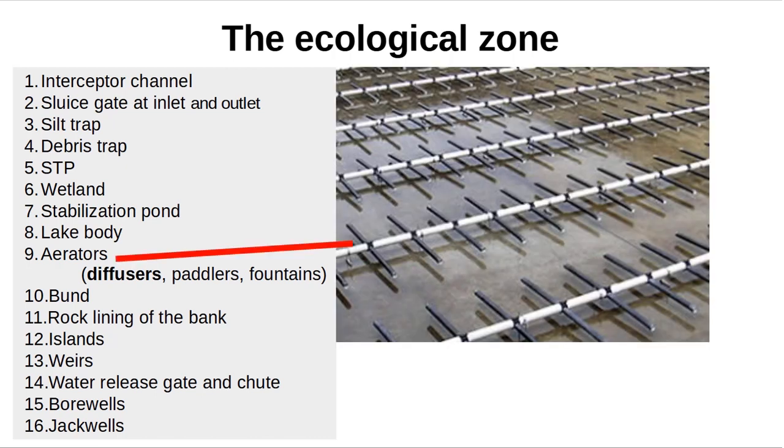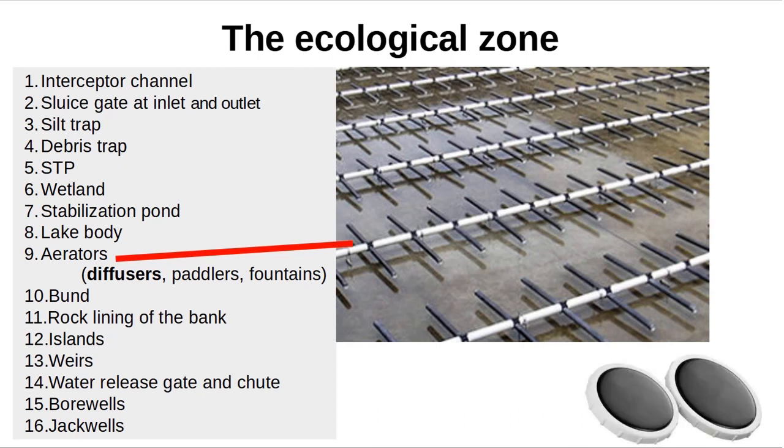The diffusers are like foam-coated perforated pipe, through which compressed air is passed. They produce a large amount of tiny bubbles, which transfer oxygen to water. Here, an array of black-colored diffusers is placed at the bottom of a tank, which is then filled up with water. The white pipe is the compressed air feeder. For smaller applications, disc-type aerators are also used.